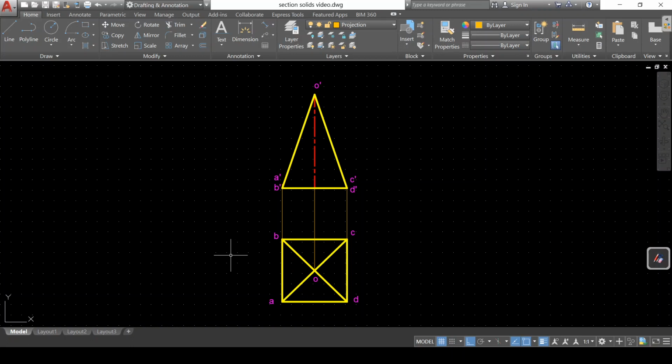Okay, so for that true shape also we don't know this length, the angle is not known. Then what to do in that case? We have to imagine that now it will cut here, but this dimension will remain the same in the true shape. Okay, that this 20 and the major side of the trapezium is 40 mm. These two dimensions will be the same in the top view apparent shape as well as the true shape. So we'll make use of this thing. So let us draw that here.